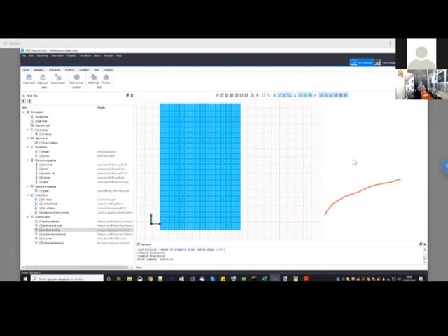And probably the last one will be on how to use micromodeling to predict the material properties for equivalent continuum models, what Professor De Risi was saying before. Because now we have the continuum isotropic model, the orthotropic adapter, and then we have a procedure to use a representative volume element and to get from these representative volume elements all the equivalent strengths in the different directions. So this one will be the last topic that we're going to cover in this series of webinars.